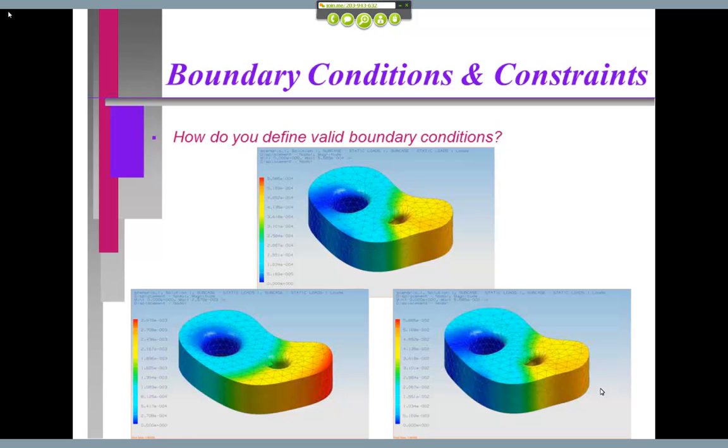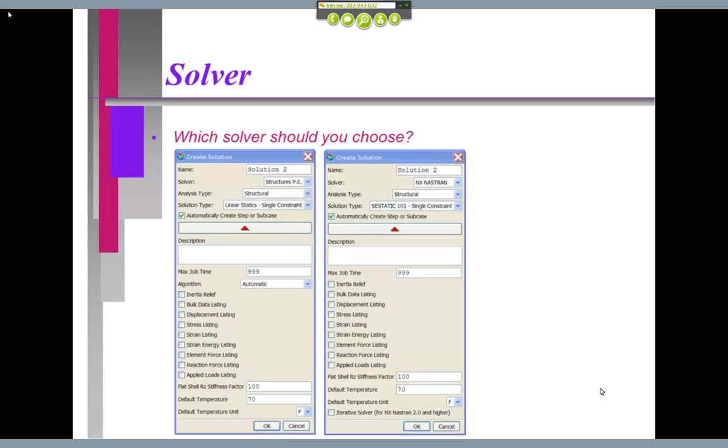Now, generally in the CAD system, you can do pressure loads, you can do point loads. They even have some superpositioning type load elements that you can put on it. So again, the point here is you need to make it realistic. If it really is hitting an edge, all of these nodes are going to share the same basic load. It's only going to apply at a single point or on an entire surface.